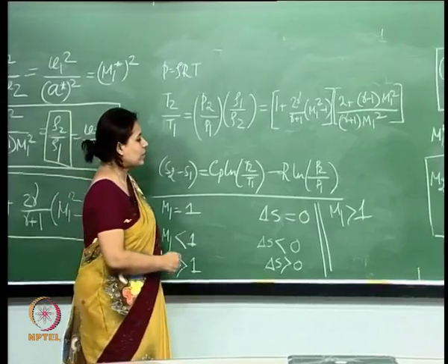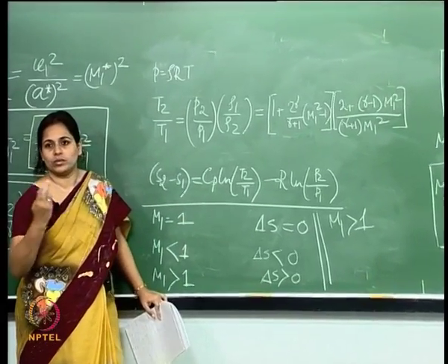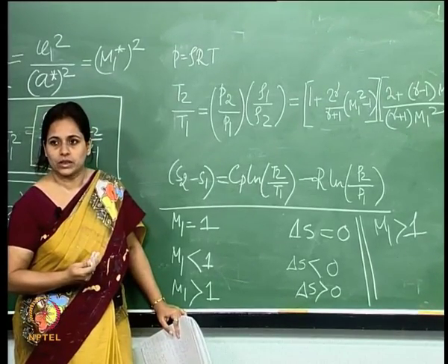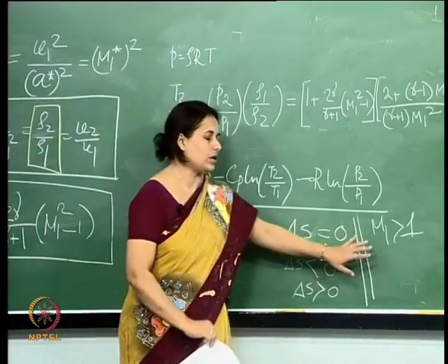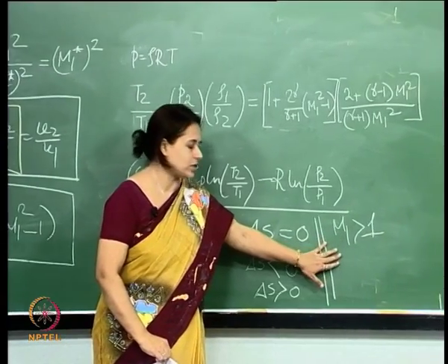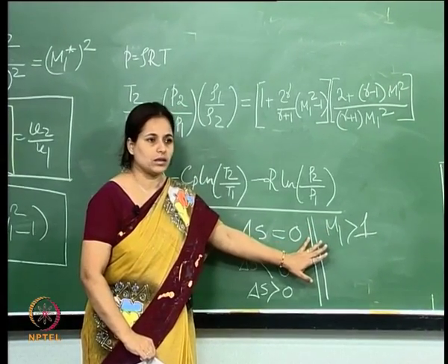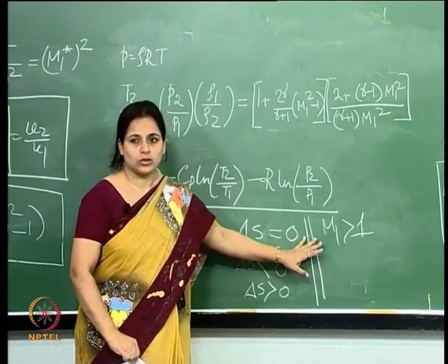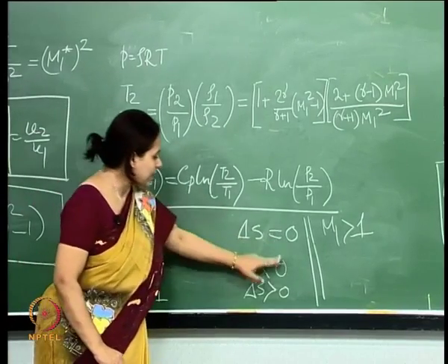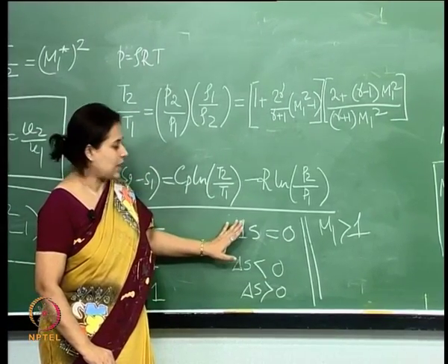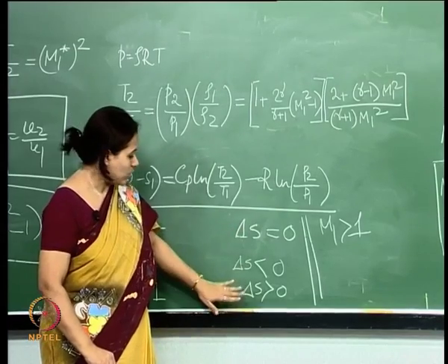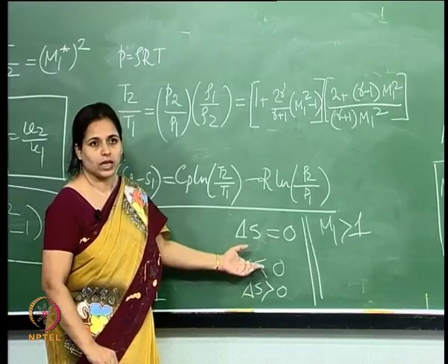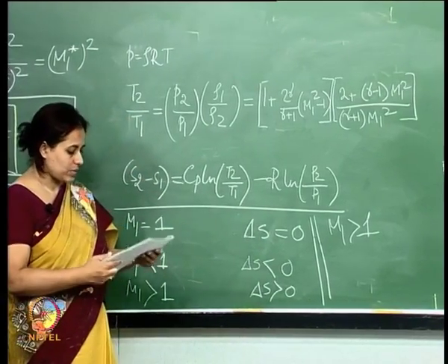As we have seen, from the relations that we developed, mathematically there are more than one possibilities, but if we invoke the basic laws of thermodynamics, we know that the incoming Mach number has to be supersonic, so that the entropy change is at least 0 or constant. So, the entropy is at least constant or increasing. Okay. That is so much from thermodynamics.